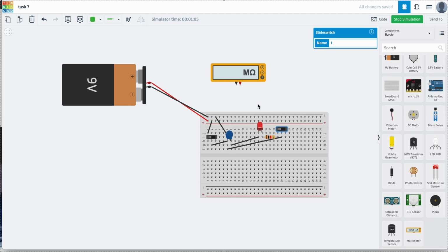So what I would postulate is that if I were to turn off my capacitor, then it would continue to supply voltage to this LED, but the LED would slowly fade out because the capacitor would drain since it's off, and it would no longer be getting recharged from the 9-volt battery. So if I test that, I turn this off, and you can see my LED is slowly starting to dim. It is very dim right now, but it is still kind of lit. So we'll see how long it takes. Now, if I were to turn this off, it would completely black out, so you can tell. And then if I turn it back on, you can see that the capacitor is still slowly discharging.